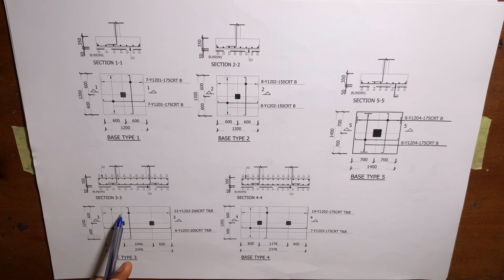So now the placement for the columns is 600 mm at the center on both sides. That is why you can see this 600 here, 600 here. The midpoint between this 600 on the width side and the center line of the length side, that midpoint is where the column post is going to be lined. So that is the alignment of the column.